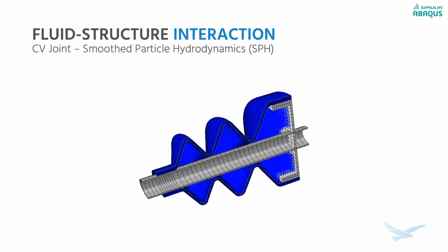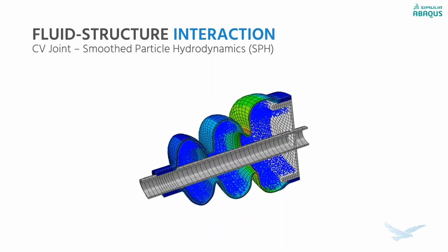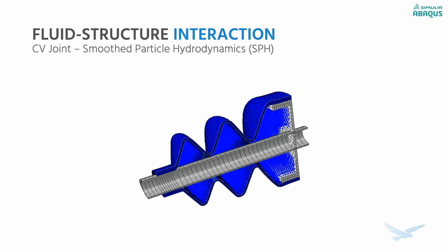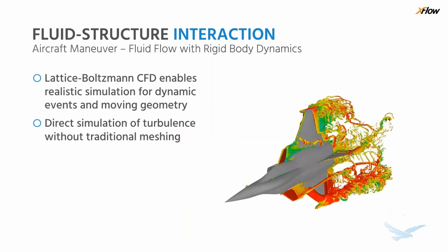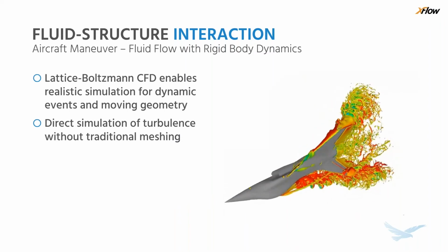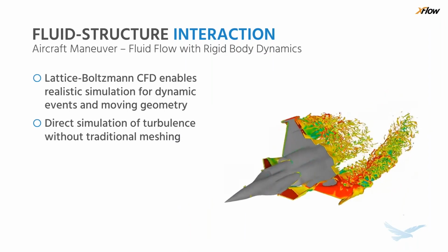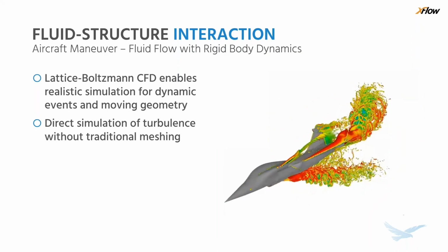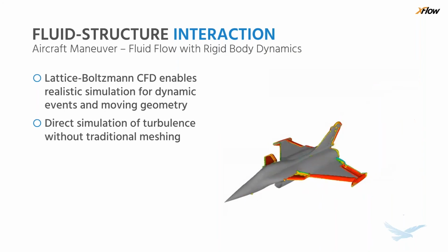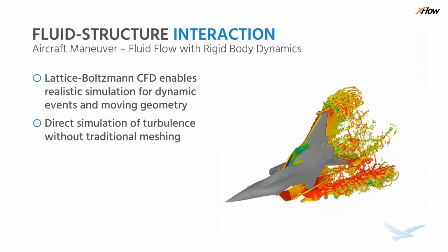And that's where you need to turn to a true computational fluid dynamics approach rather than one of these finite element analysis approaches. This example here, we've got something that's really, really turbulent. And as we mentioned before, XFlow is a really good tool for that. Right? It uses lattice-Boltzmann CFD. And so it works well for these transient situations with really dynamic flow.